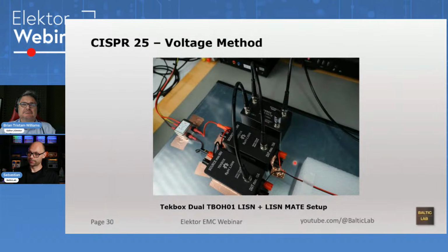I hope everyone's familiar with common mode and differential mode, but a very brief recap: signals, the way we usually know them and learn them in school and university, travel in opposite directions. Like here, you'd have the positive supply going that way and coming back that way. At least from the technical standpoint, I know electrons flow that way and come back that way. Common mode would be both signals, like noise coming from over here, traveling on both lines, same direction, same phase, same amplitude. And so this is separating common mode and differential mode, so we can measure them independently.